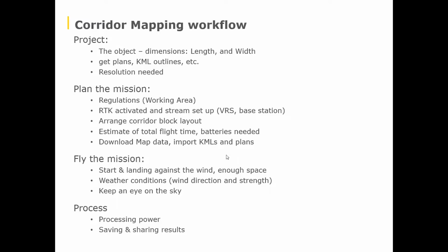For flying the mission, basically it's as usual: start and landing against the wind, enough space, weather conditions in general, and be aware of the sky. Just control your airspace. If you have someone entering your airspace in an aircraft or another drone, you need to be ready.